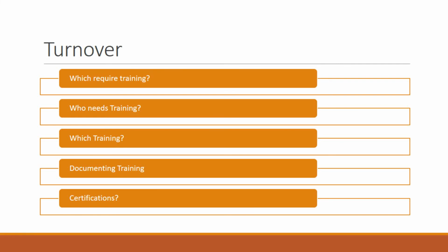Now, other things that you also need to consider are the documentation and the project closeout. A project is not finished until all related paperwork is finished and given to the right people. And this covers operations and maintenance manuals, as-built drawings and specifications, etc. The documentation must be complete and organized so that it can be easily found and kept. To make future renovations simple, think about using electronic documentation or drawings such as CAD files or PDF files.